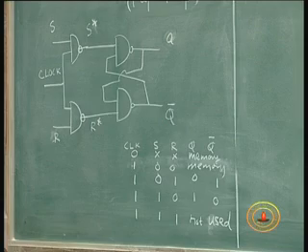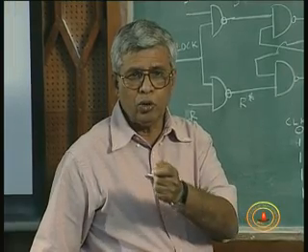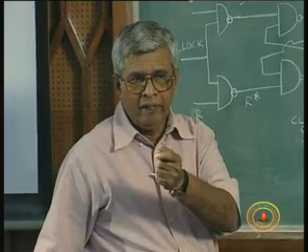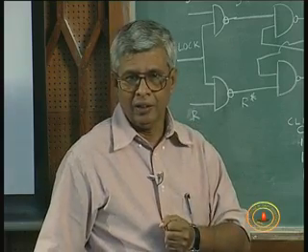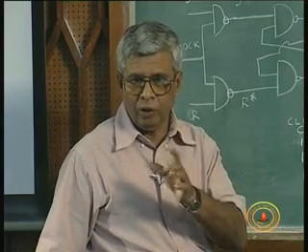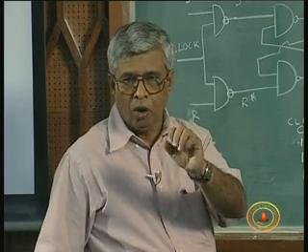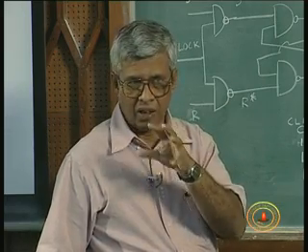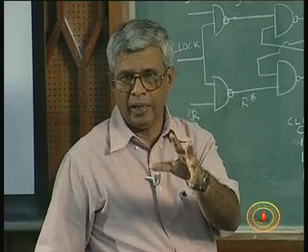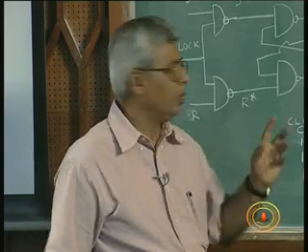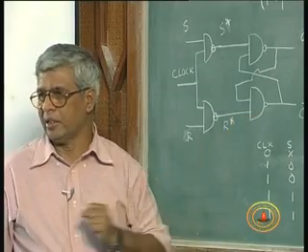So this clocking is a gating signal or an enabling signal which lets you decide when to put a new value of the input and store it in the latch. After putting it, if you do not want the value to change for a while, you want to keep it and use it later on, all you have to do is disable this gate, or make the clock 0, and then it will continue to be stored as it was, and any changes in the input, accidentally or intentionally, will not affect the storage.